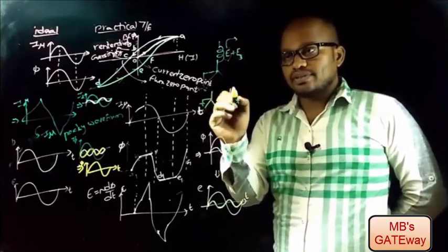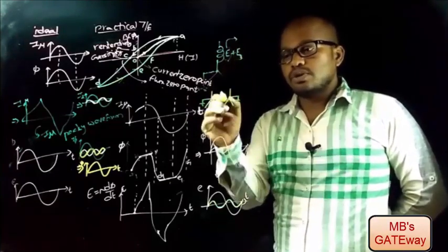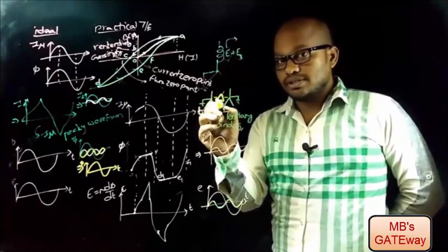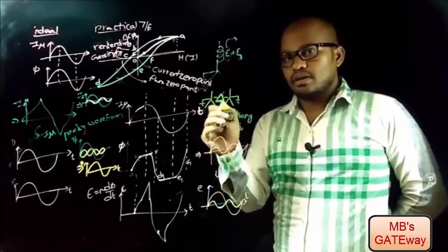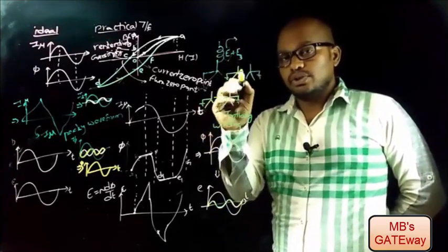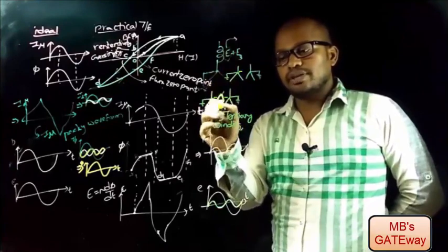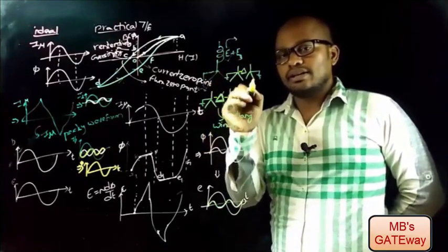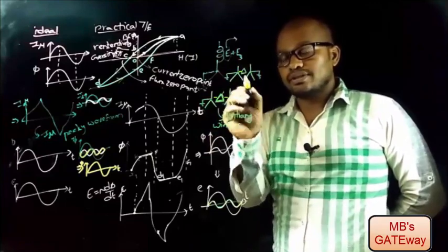Similarly, in case of three-phase transformers, third order harmonics are reduced by using a tertiary winding which is connected in delta. Actually, three-phase transformers are to be represented like this, but to reduce the third order harmonic we make use of a tertiary winding. That is why a delta representation is also used in this representation.